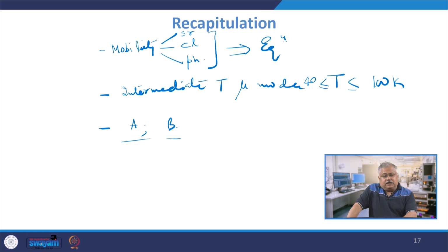So by the end of this lecture, just looking at the expression of the mobility, you would now be able to plug this mobility model into the current equation to get the overall current, such that the current is now depending on a mobility which is field dependent and temperature dependent, right. So by the end of this lecture, we will be able to extract the value of current given electric field, given substrate bias, given temperature, and given the structure of the device.